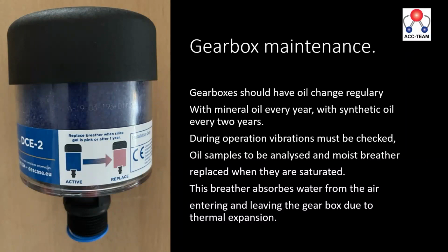One of the things that yesterday we also heard is that water in the gearbox is a very, very dangerous thing. That's why nowadays most gearboxes, we already do this for more than 10 years, we supply with breathers. Those breathers have silica gel inside, and it will filter out the water vapors, because due to temperature changes, you get air going into the gearbox and air going out of the gearbox. If you don't trap the water vapors, you will get water in the oil, and that is damaging your gearbox, your gears.